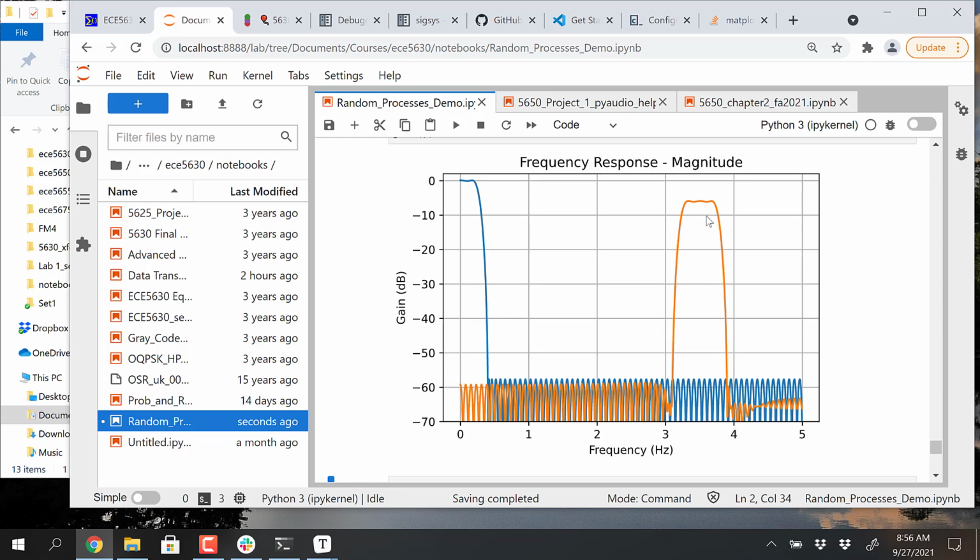I just wanted to give you a little idea about how you could build up things if you're needing to build a simulation. Most of the time, we won't do this at all. Everything will be treated right down there at baseband. It might deviate about zero frequency, but we're not going to try to create a carrier-based system. We're going to model everything as if it's down at complex baseband, which in the DSP domain just means the front-end receiver has complex frequency shifted the signal from a high-frequency carrier down to something very close to zero. It doesn't have to be exact. It's just in that neighborhood, and then it can get processed at the front end.